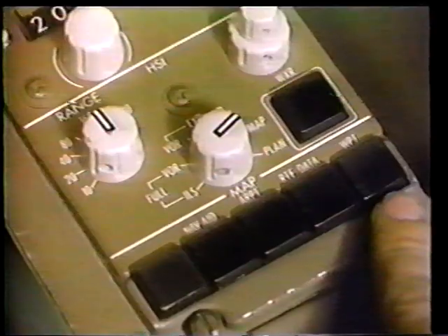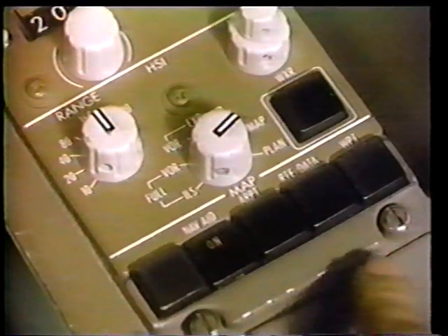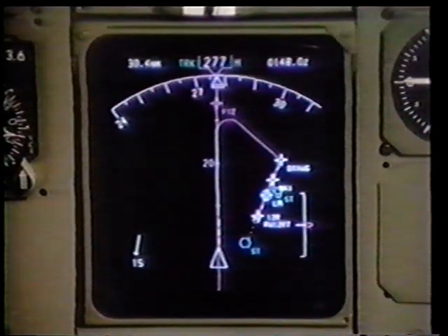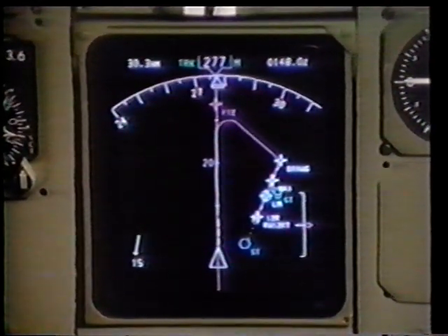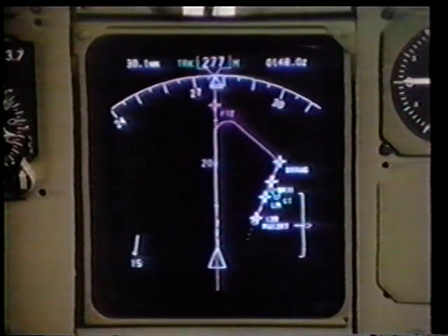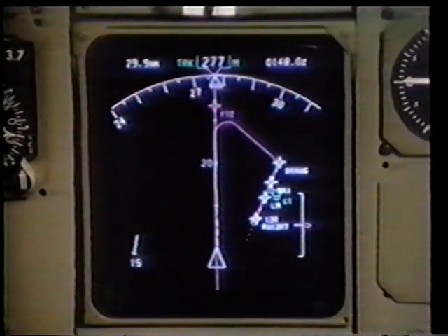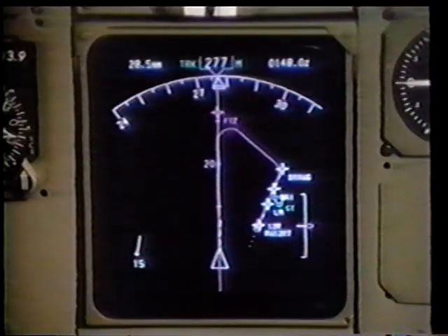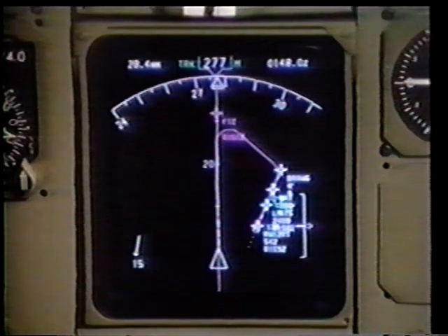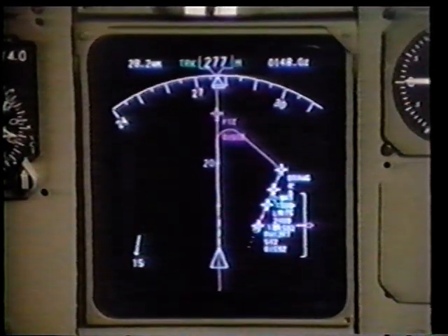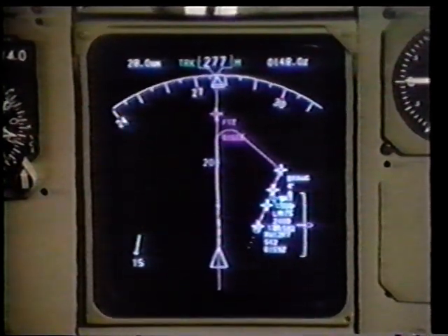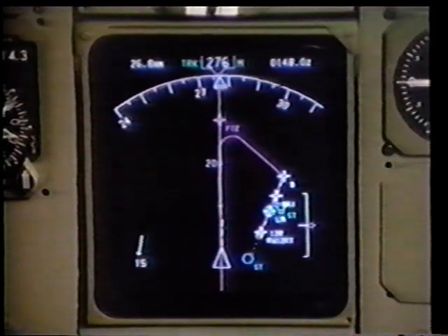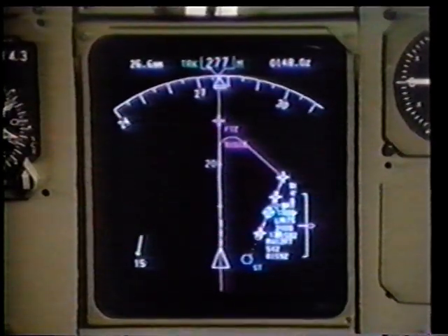The map switches allow selectable information to be displayed on the EHSI in the map mode. For example, pushing the Nav Aid switch brings up additional navigation stations on the selected map segment. Pushing the map switches a second time removes the added information. When the route data switch is pushed, mandatory crossing altitudes and ETAs for the flight plan route waypoints appear adjacent to these waypoints. The map switches may be selected individually or in combination. This enables the crew to control EHSI display information and clutter.